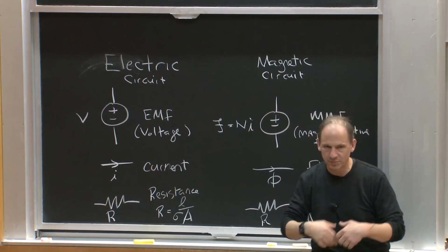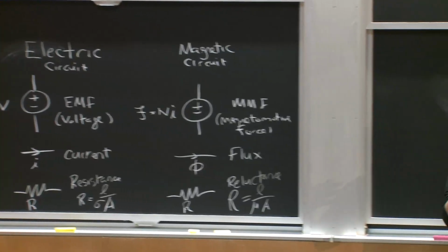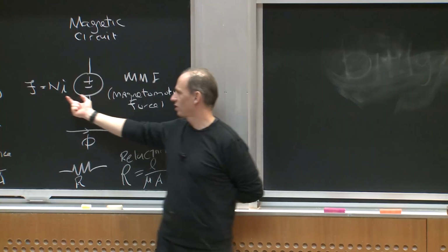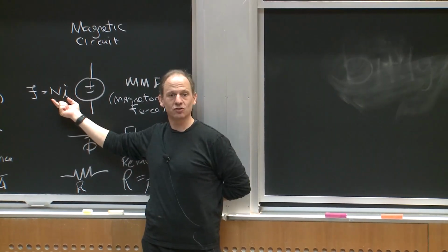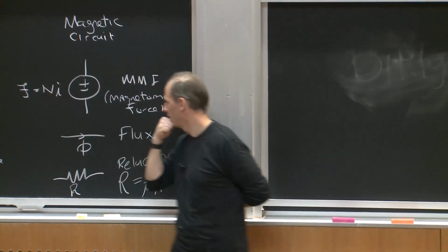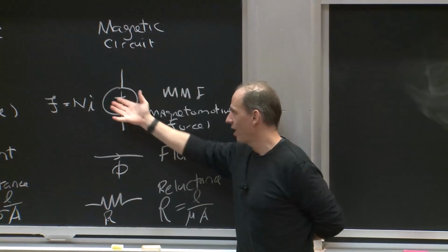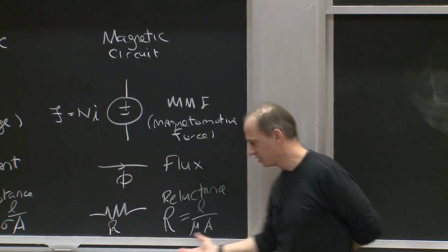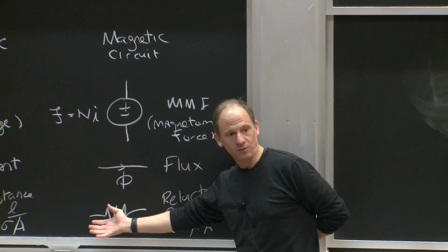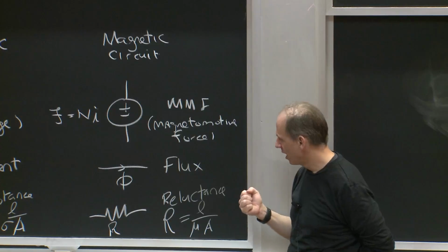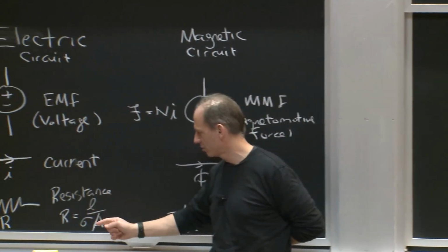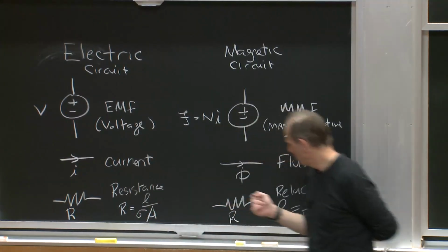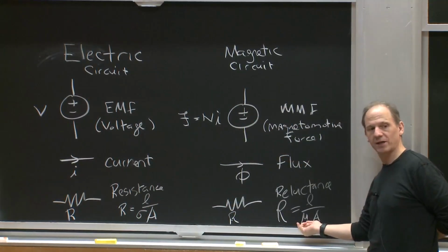And we said we can build a magnetic circuit that describes magnetic structures where we have an MMF, which is usually the ampere-turns trying to drive flux. Flux is our through variable, so MMF is our across variable, flux is our through variable, and reluctance to magnetic flux depends upon the material and the geometry. And just as an electrical resistance is the length of the resistor divided by the area and the conductivity of the material, permeability is just conductivity to magnetic flux.